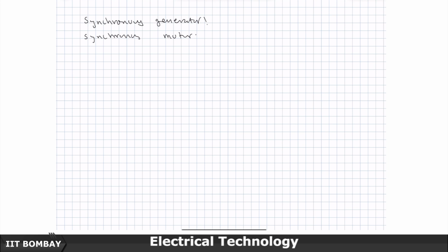But when we say generator, what we are trying to focus on is the induced EMF in the stator winding. The rotor has a magnet, either an electromagnet or a permanent magnet, usually an electromagnet. How do you create the electromagnet? You create it by sending DC current. So, your omega r is therefore 0, and you rotate the shaft at synchronous speed.